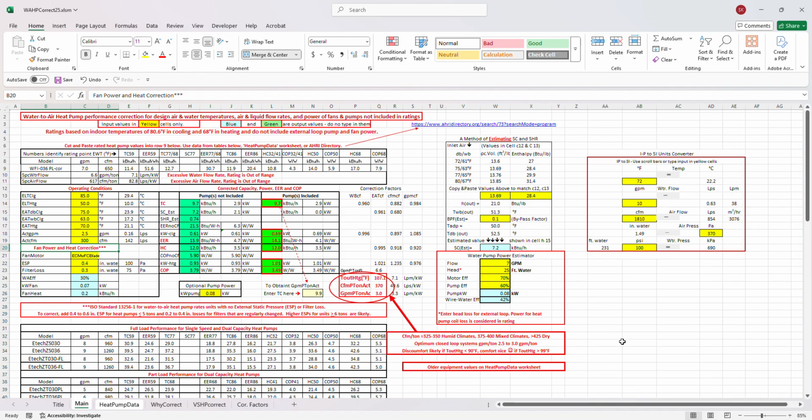But what we'll do this time, you paid this extra money for a variable speed machine, why don't you just go ahead and get a variable speed pump, so when the thing goes into part load, you can drop it down. So let's change this to 2.5 GPM, and of course, when you lower the flow rate, you're also going to lower the head loss. So let's put this down around probably 8 foot of head. Okay, efficiency is still about the same. The machine is pretty flat. Okay, so what do we got here? We got 370, 107, nice and hot air, 3 GPM per ton.